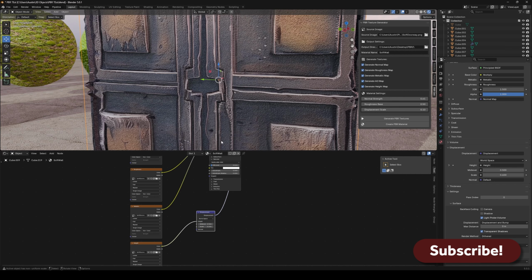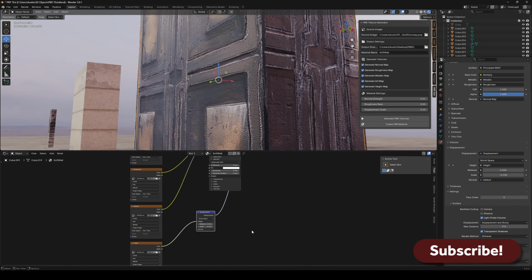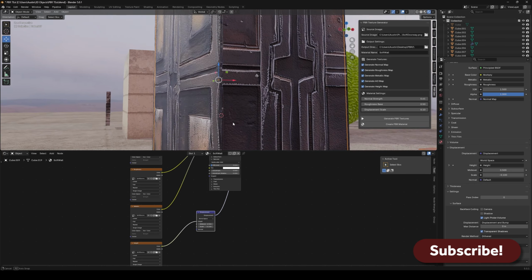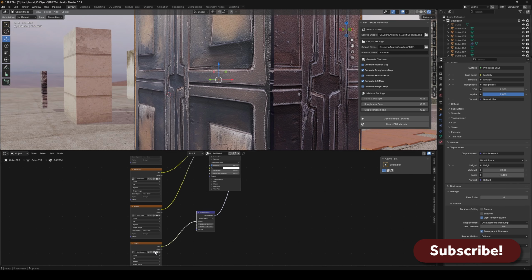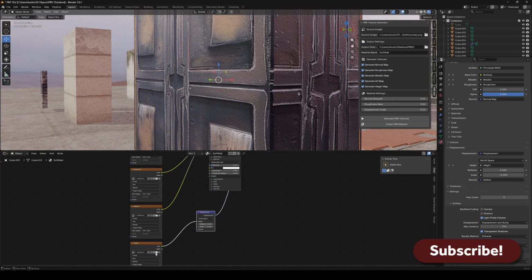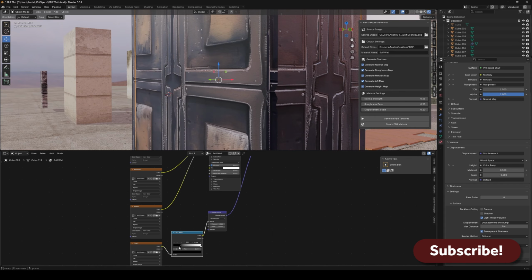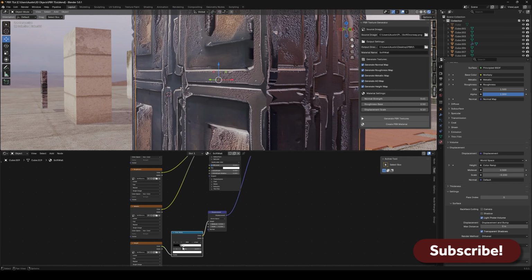If I switch it to world space, does that help? No. We do negatives. This is really what I would like is for these to be popped out. We can come in here and look at our maps. This is our height map. So what we do with that is if it's giving us this result, add a good old color ramp. Bam, right there. And what we could do is we can kind of control a little bit more about how it's popping out.